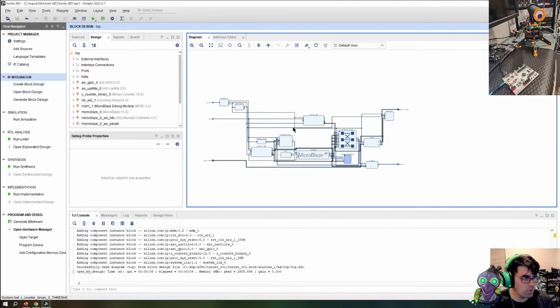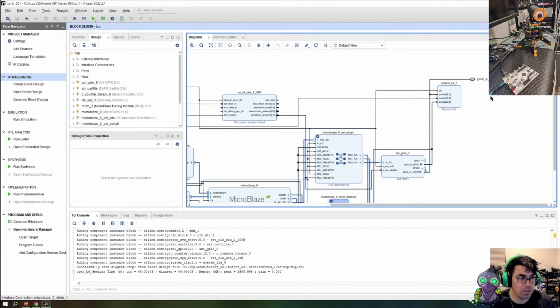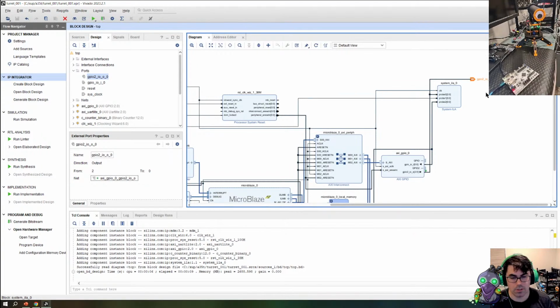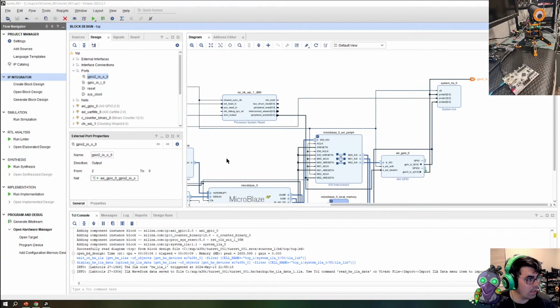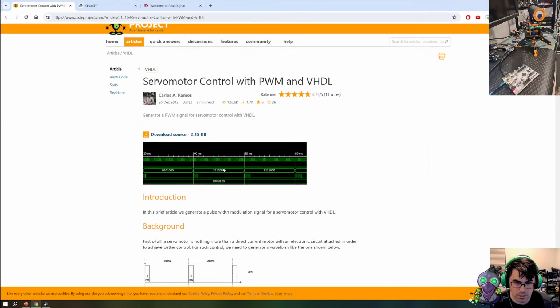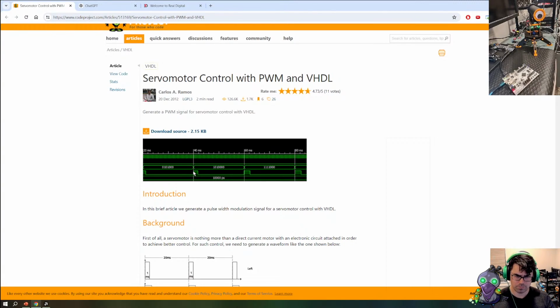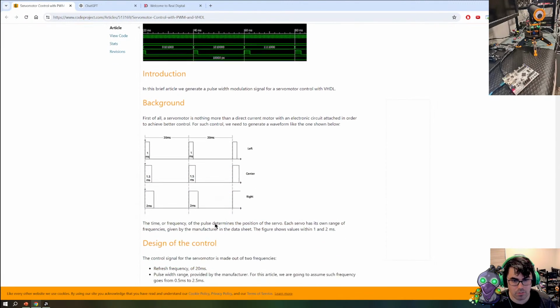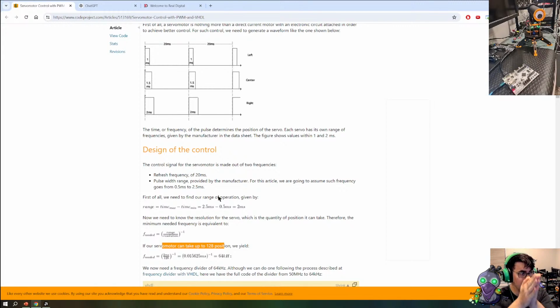Okay. Let's go to the fun now that we have everything set up appropriately. So we want to play with the servo sensor here. That's just a single line. So let's go ahead and work on the servo control. So servo control uses pulse width modulation over a 20 millisecond period. You provide a specific width of the pulse, and it will do a fixed change. If it's a fixed servo, it will go to the same position every time, I believe. And if it's a continuous servo, it will do a difference based upon the current position.